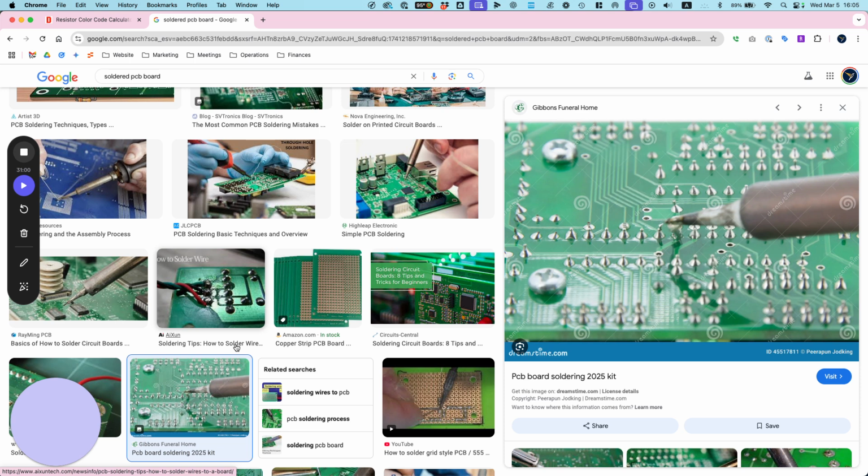16.8 volts. Now, when it's discharged, it's going to be 3.2 volts-ish. I don't know, you kind of want to target more like 3.3, but I'm just going to say this. Times 4 cells, what is it going to be when it's discharged? 12.8, right? Do you see that?